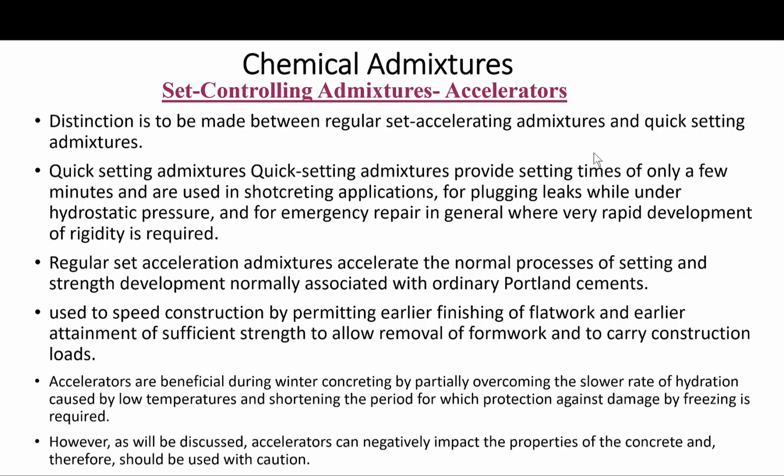But we could use the accelerators in order to overcome this issue and basically get rid of this inconvenience. However, as will be discussed, accelerators can negatively impact the other properties of concrete, and so they should be used with caution. And again, really, this is almost with every admixture. All right.